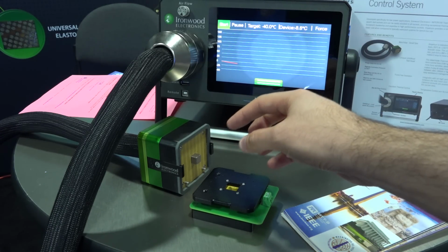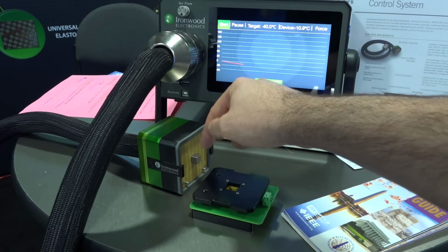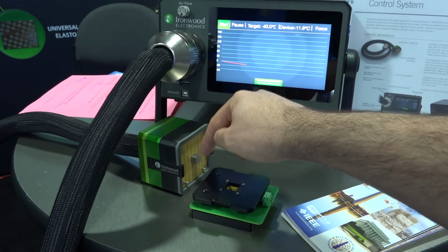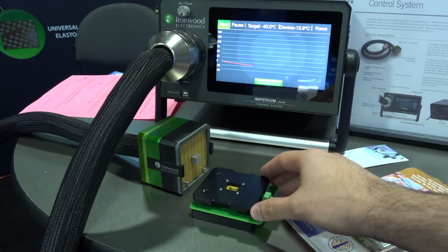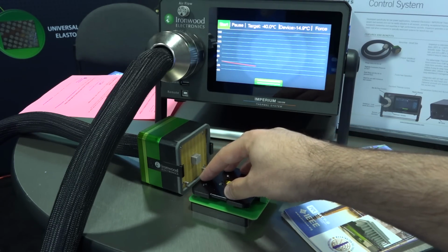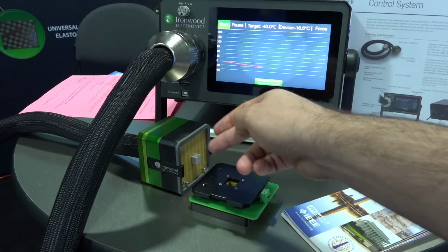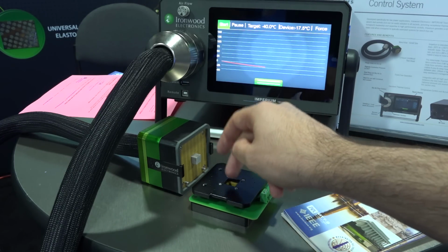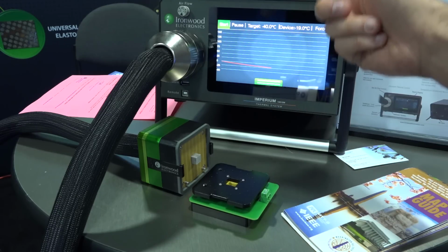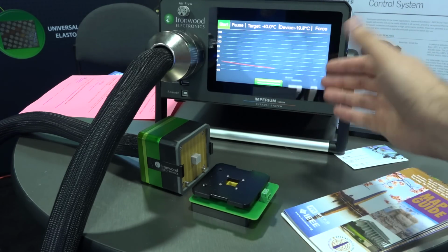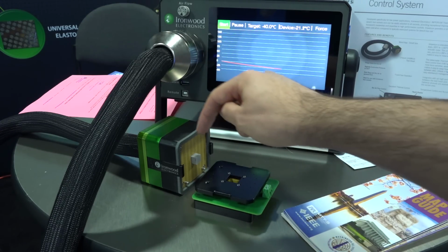This system allows you to not have to put something in a temperature chamber because you have this localized low thermal mass head. The low thermal mass also means that it's comparable to your device under test, so that enables the really rapid up and down temperature cycling. So with the appropriate socket, you can imagine putting a die in there with a direct connection with a very low thermal resistance between those two, so the temperature of your die and the temperature of the cold head or the hot head will be pretty close to each other. And you can cycle this up and down across 100 to 200 degrees, which is quite a lot, and it can happen very fast. It's a pretty cool form factor.